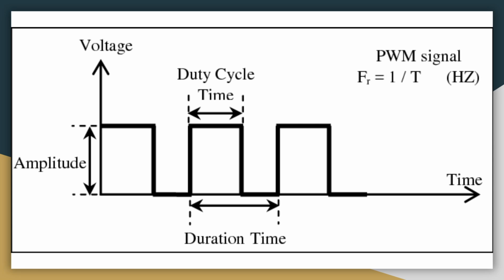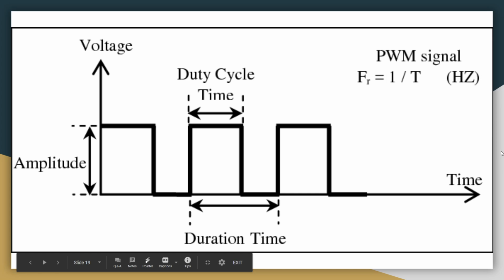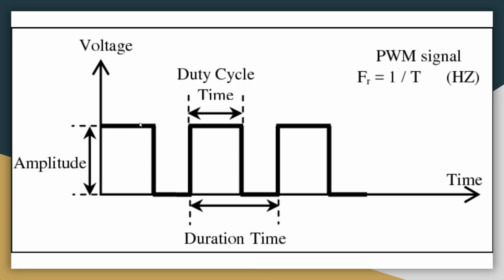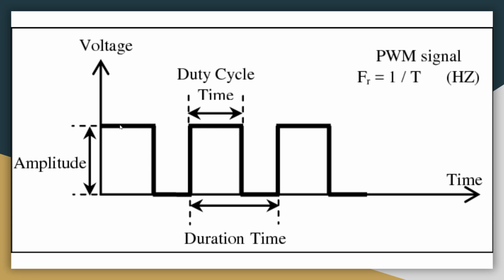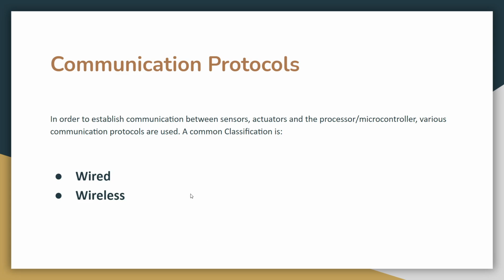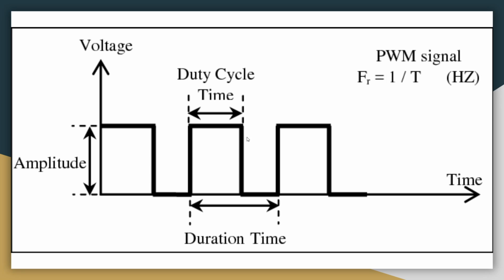So what I'm going to do is try to generate 4.8 volts throughout a duration of time. So for example, say I want to generate an average of 4.8 volts for 10 seconds. How that works is my microcontroller keeps on switching on and off the output voltage of 5 volts regularly. For a small amount of time it's 5 volts, then it suddenly becomes 0 volts and stays 0 for some time. It again becomes 5, it again goes down to 0.